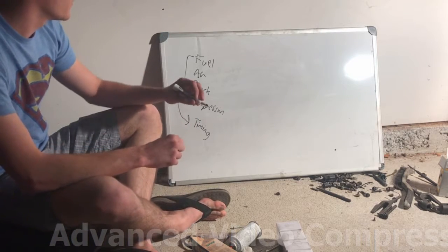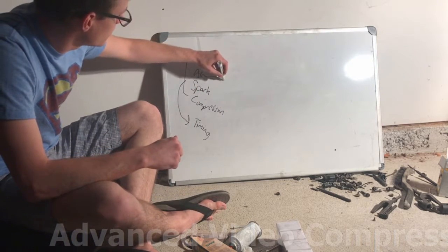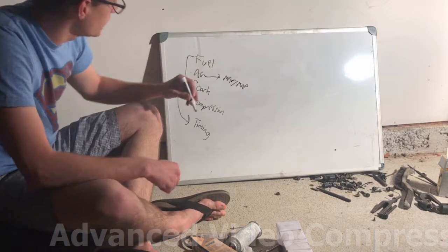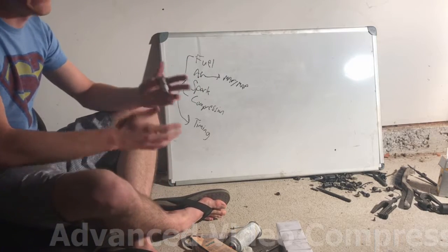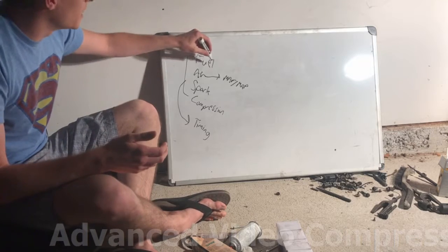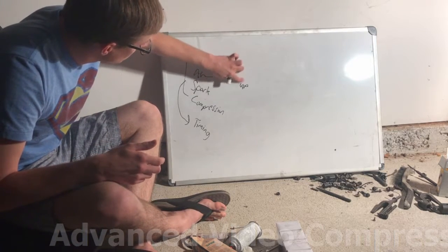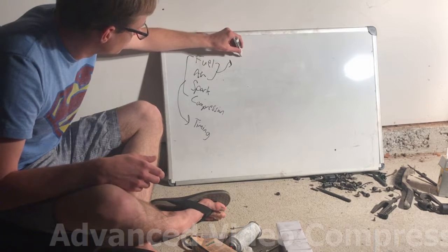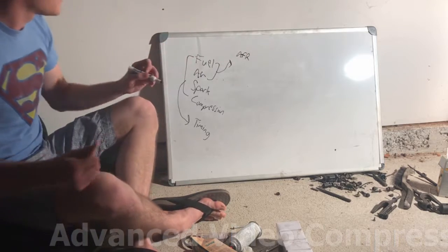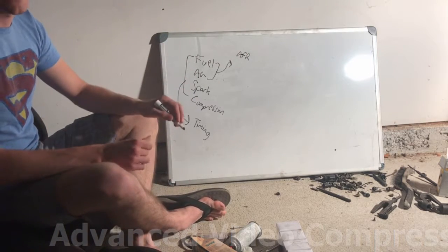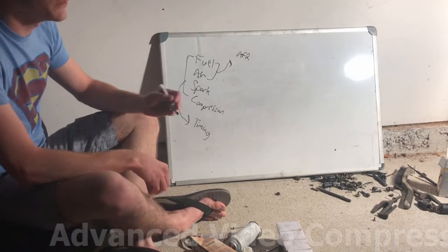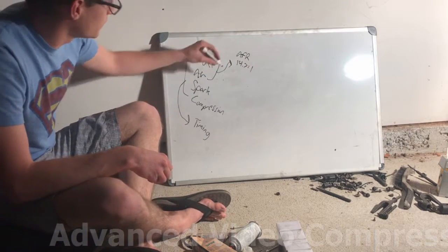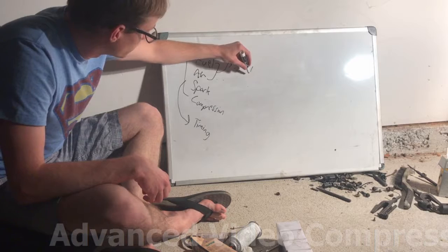So since we're talking about air, specifically sensors that control airflow to the engine, MAF and MAP sensors, we also need to talk about fuel, since there's a delicate relationship between fuel and air, and I like to call this a car's air-to-fuel ratio. In shorthand terms, the AFR. So most cars at ideal operating conditions have an air-to-fuel ratio of about 14.7 to 1. And that's going to be 14.7 parts air to 1 part fuel.